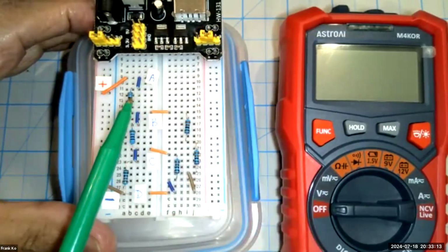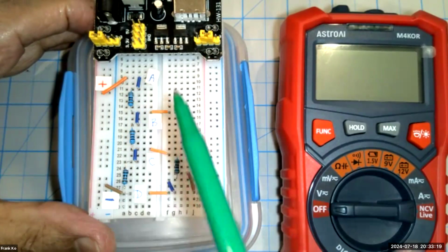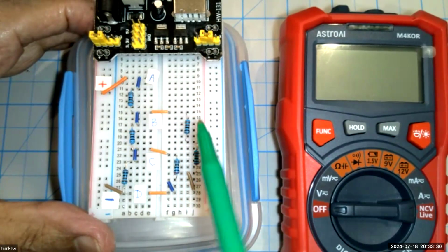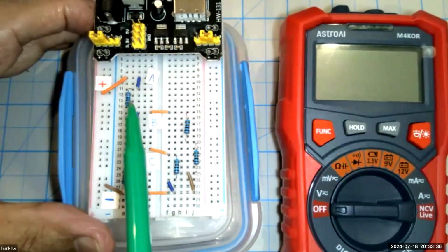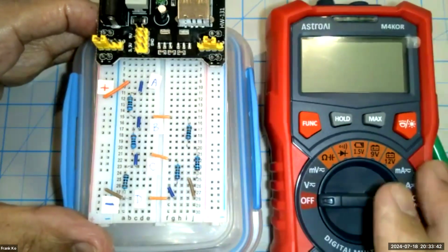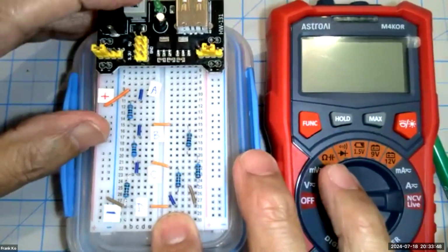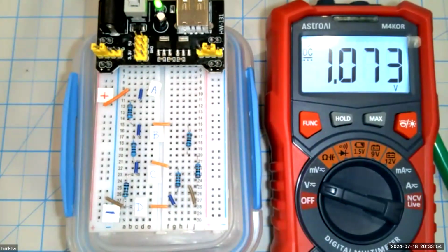I still have three resistors, R1, R2, and R3, although these are different values now. I still have a point A, point B, point C, point D. I still have an R4 that is attached to point C, requiring 2 volts. We still have an R5 of 4 k ohms, requiring 4 volts, which we hope to see at point B. So now with the new resistor values that we recalculated, all this should work out very nicely. And let's see what happens when we turn everything back on. So I'm going to light this guy up, turn on the multimeter, and now let's see where we stand.